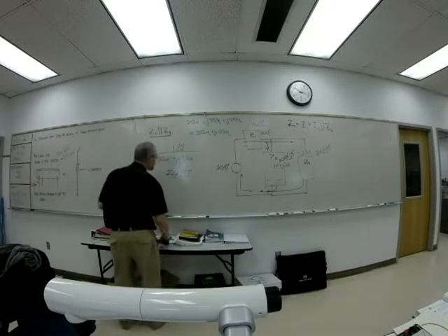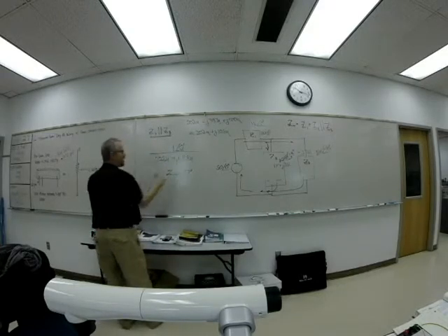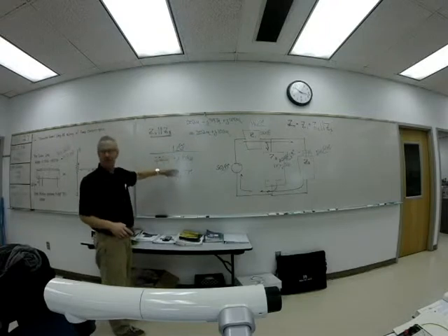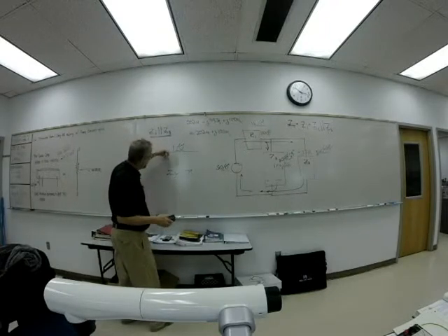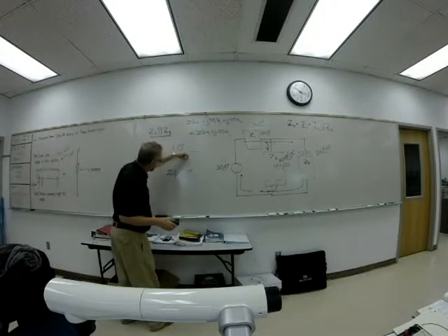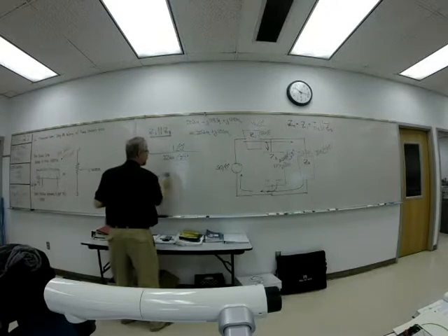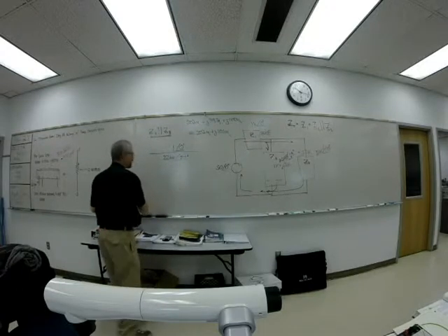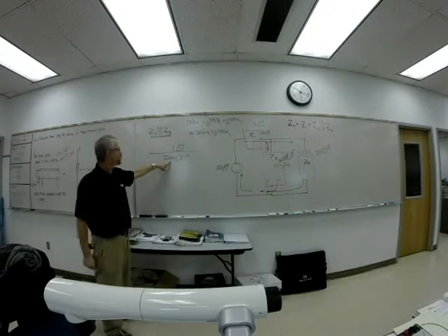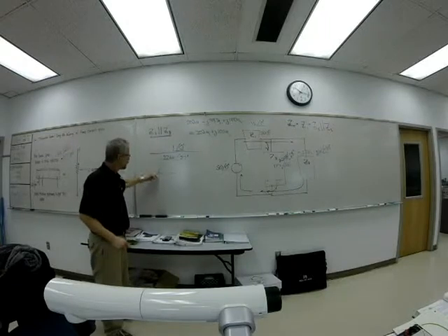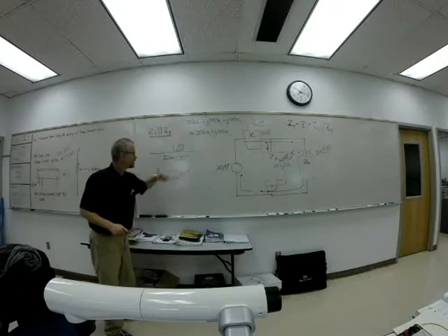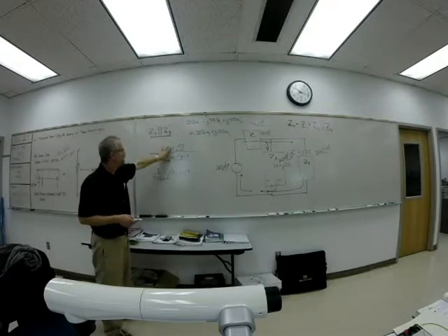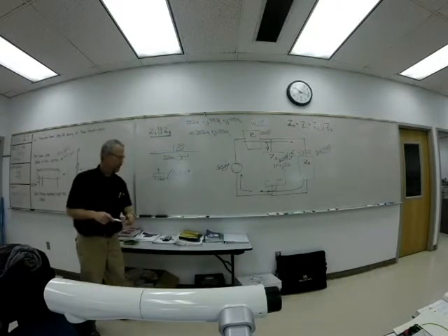Okay, so this is the same as that, isn't it? These two the same thing? Yeah. So I can replace this with that. 226 micro at an angle of, is it 27 degrees positive? Yep. Okay. 1 over 226 micro at an angle of 0 minus 27 degrees. That's the math we do. We divide the coefficients, subtract the angles.